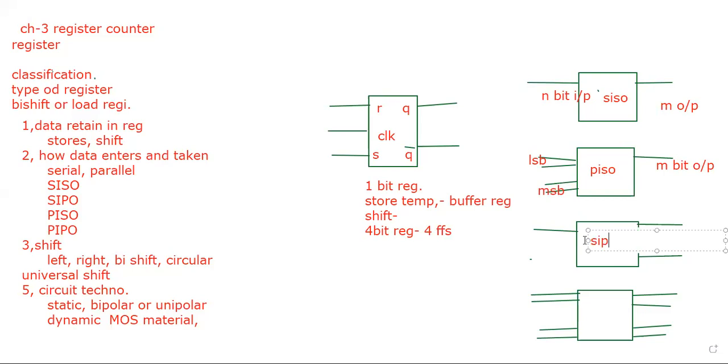This particular one is SIPO, and this is the convenient one, but PISO is the most difficult one in the real sense, because all are entering, but you are sending out only one data. Simultaneously four enter, but you have to deal with only one. So it would be a bit complicated, or we need an extra circuit to achieve this model.